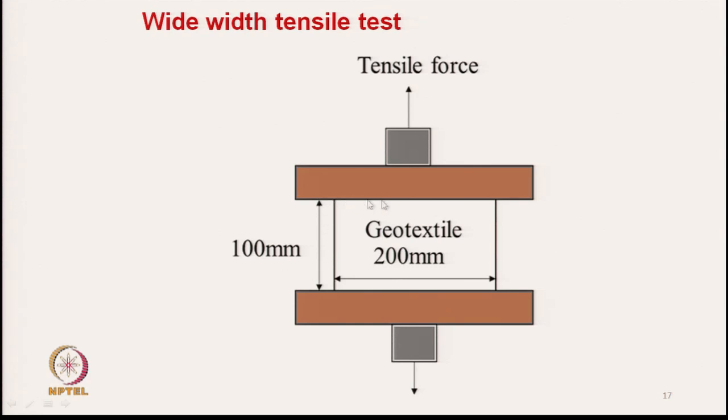So, due to this wide width, the Poisson's ratio is restricted, and the result which we get here from wide width tensile test simulates the actual field condition.